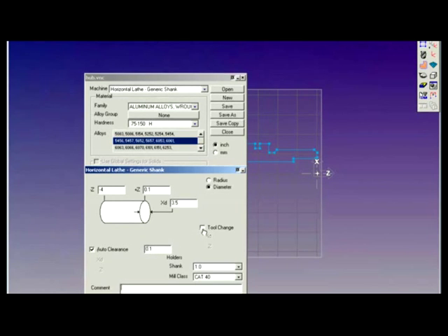The tool change checkbox, when activated, gives us an absolute position based on part 0. Tool change position is handy when working with very short work that is barely protruding out of the chuck, and you don't want to travel all the way to home to index the turret.